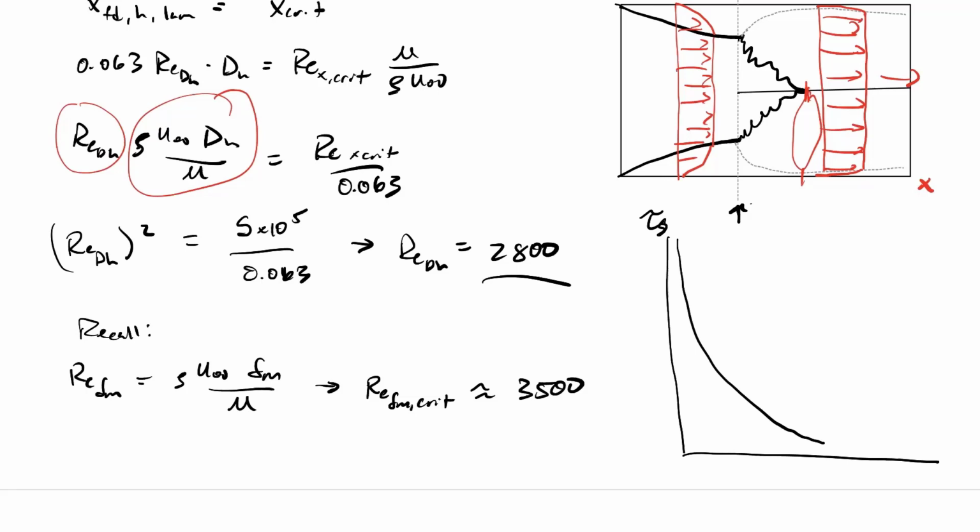As you get to a turbulent transition region, it starts going back up. Then once it's fully turbulent and fully developed, the shear stress at the wall is not going to change anymore. And this gets exactly to that question. So this shear stress for X FD is not changing anymore.